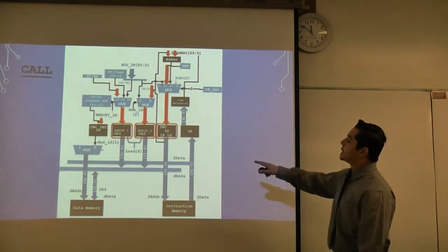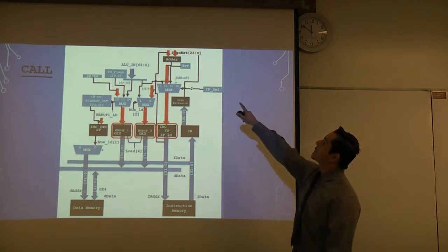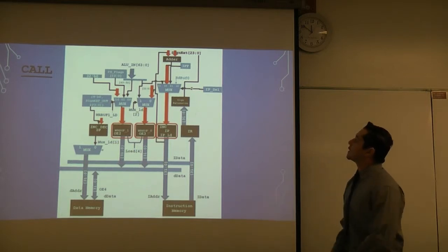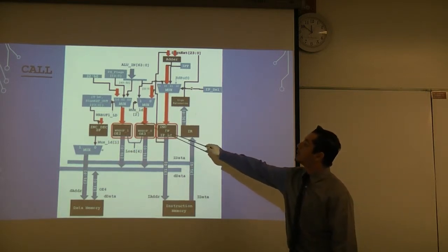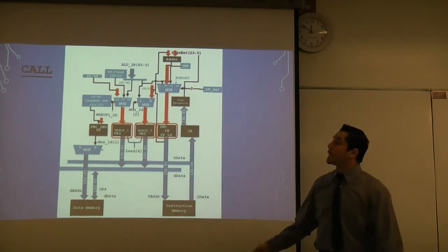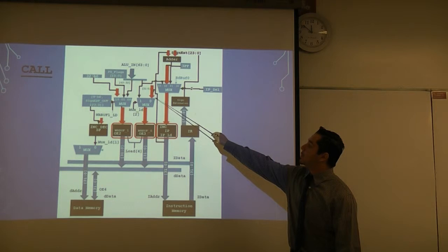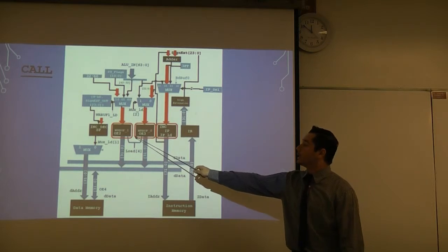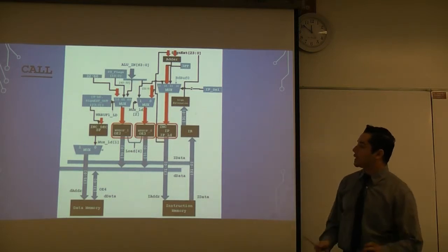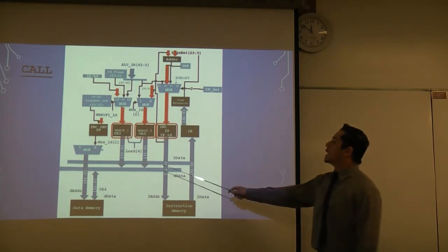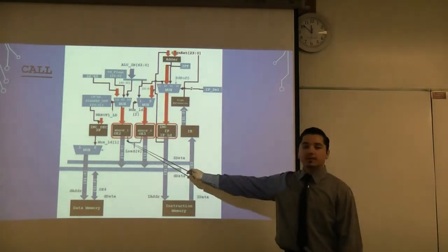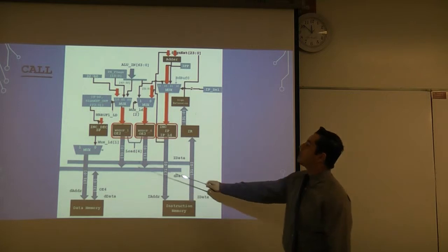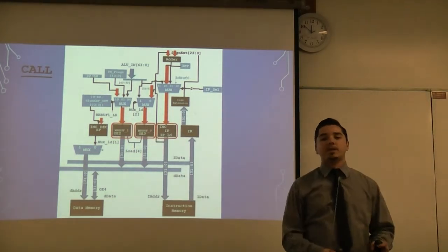So on the first state, you're pretty much handling all of these things to go on. So you're grabbing the sign extension 23 to 0, and you're adding that to the value of the IP. You have to make sure that your mux loads are enabled, so then you're able to use this mux, and you're going to be setting it at 0, so you know that you're going to be grabbing the IP. You're also going to be loading the write buff, the lower part and the higher part, the 32-bit most significant and the least significant. And then on the higher part of it, for the 63 to the 32, you're going to be grabbing just the 32 bits of 0, because you're only grabbing the IP that you want to be storing onto the stack.